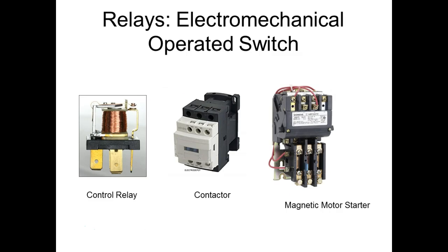Hopefully it won't break. These are the types of relays we have. We have what we call a control relay. What we'll find is most control circuits deal with two different sections. In fact, we'll look at it. We have a control section, and then we'll have a power section. Now this was done a long time ago because the control section, for years, was like 120 volts, but now just about all your controls have dropped down to around 24, 26 volts.